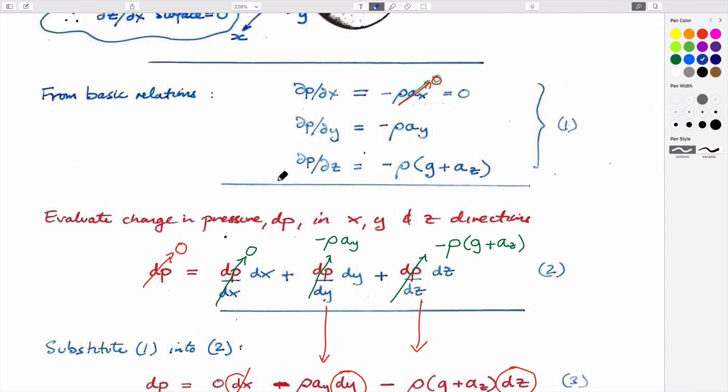So we know from before that if we take this expression here, this is the expression that gives us the change in pressure with depth is equal to minus rho times g. But now we have this additional term that comes into this, right? This expression here. And so usually this term here is 0, and this has just been equal to minus unit weight.